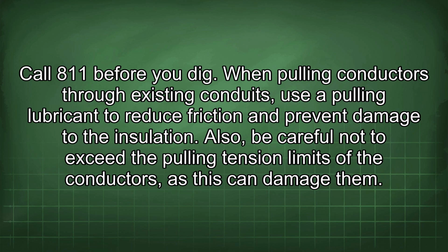Call 811 before you dig. When pulling conductors through existing conduits, use a pulling lubricant to reduce friction and prevent damage to the insulation. Also, be careful not to exceed the pulling tension limits of the conductors, as this can damage them.